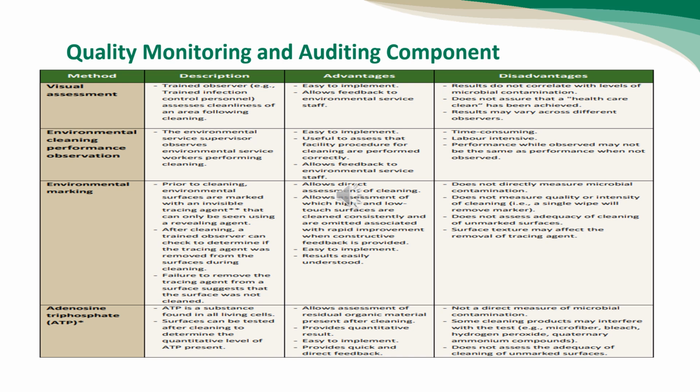Advantages for this method are it allows assessment of residual organic material present after cleaning, provides a quantitative result, easy to implement, provides quick and direct feedback. Its disadvantages are it is not a direct measure of microbial contamination. Some cleaning products may interfere with the test and it doesn't assess the adequacy of cleaning of unmarked surfaces.